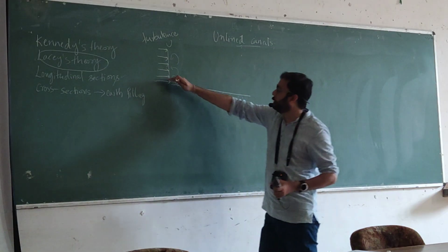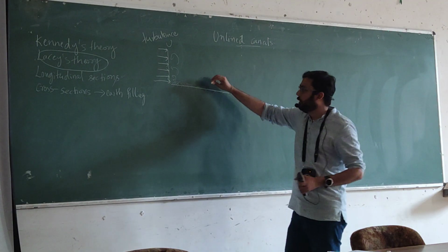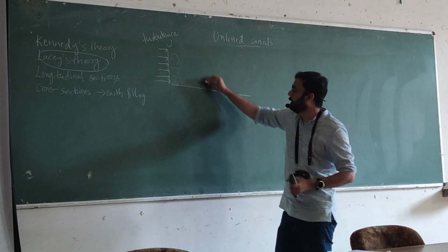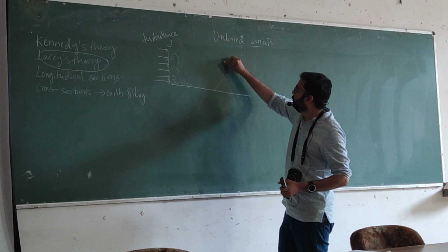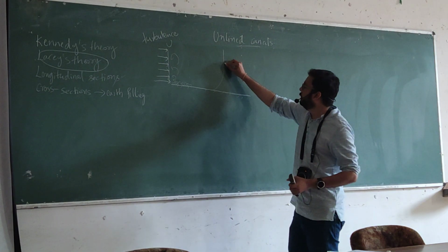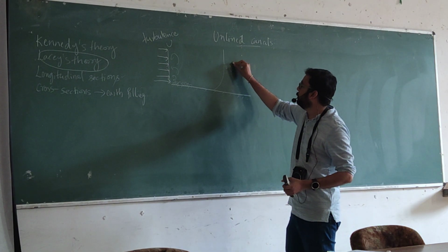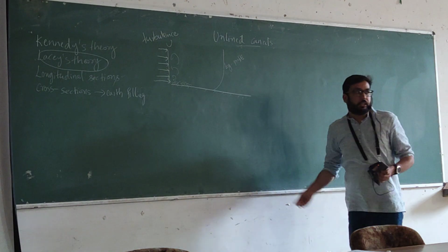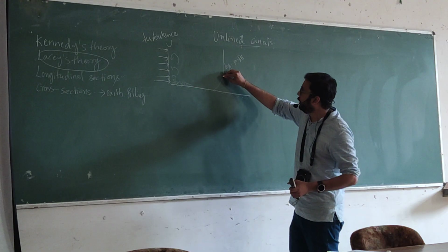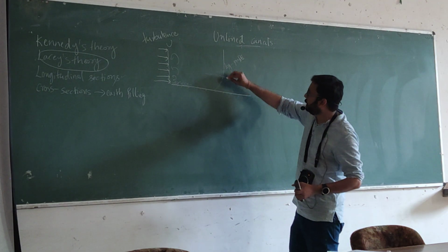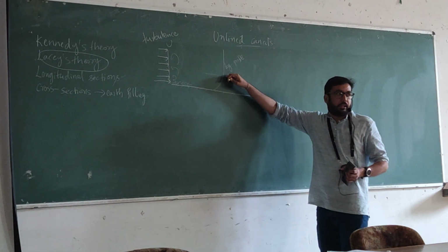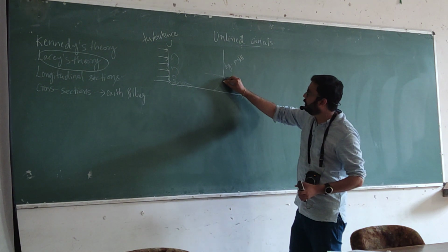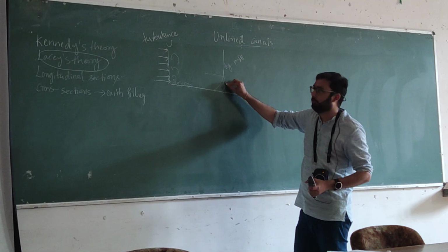So as the flow is moving on top of the sediments, you will slowly start to see that the uniform velocity has changed, and then ultimately it would reach a logarithmic profile. And in this layer the velocity would be increasing from the bed, and after a certain height it becomes constant or uniform. So this you might have heard of as the boundary layer.